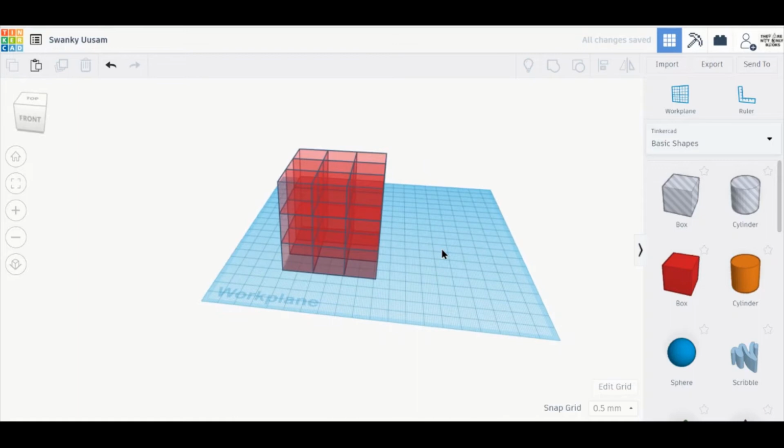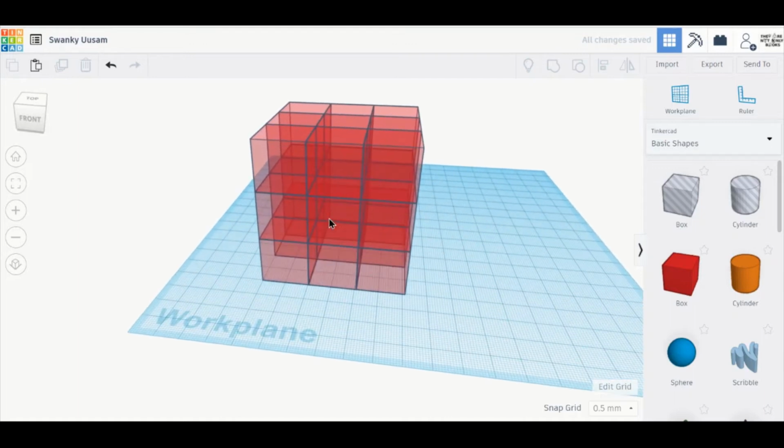Let's start by making our first puzzle piece. We're going to be connecting these 4 pieces. Normally, you could just group the pieces you want, but because we have that 0.5 millimeter gap between all the objects, we have to go through a little more to actually connect the pieces before we actually group them. This is done by stretching the shape so that they intersect with the piece that it's trying to connect to. We then group the cubes we are connecting by selecting them and pressing the group button, and then moving it off to the side so we can see what pieces have been used already.